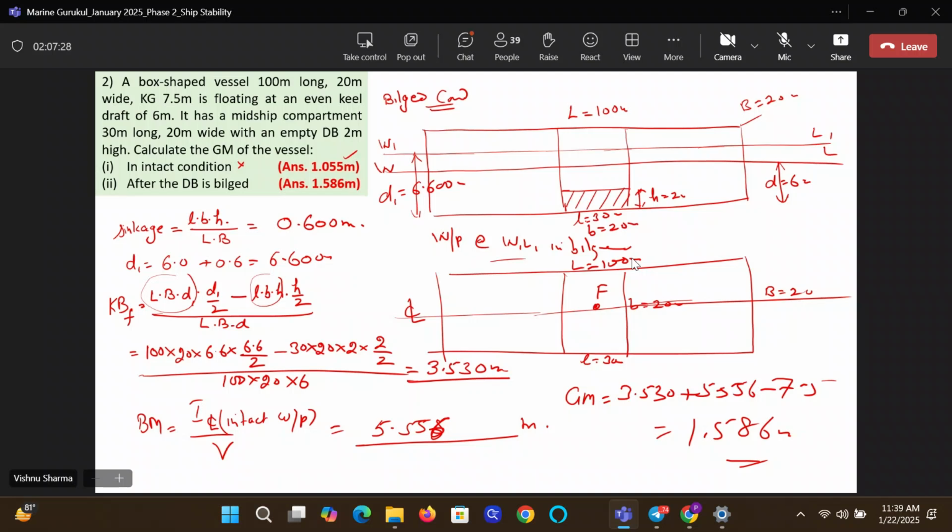See, I don't want to make any very express statements on overall stability of the ship. Overall stability comprises static stability, where GM or GZ is the criteria, including the transverse stability, where the list or the heel is the criteria, and the longitudinal stability, where the trim comes into picture. So you have to take a holistic view of stability. Yes, if you're talking of GM, GM is definitely increased. There cannot be two views on it, right?